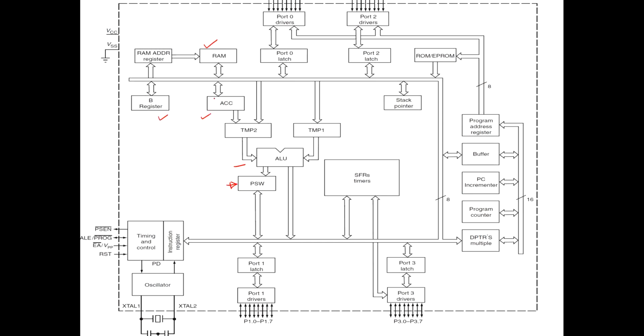It is an 8-bit register, widely used for addition, subtraction, multiplication, division, and other Boolean bit manipulations. The A register is also used for data transfer between the 8051 and external memory. We have an external memory of 64 kilobytes, from which we can access data or store data.